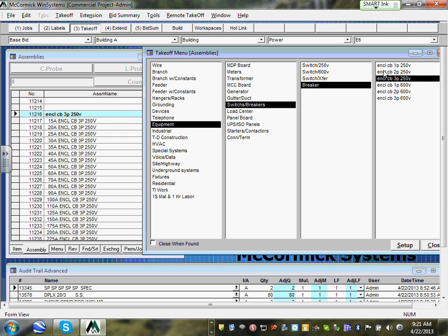Reminder, my friend, this project is 208. If it's a 208 system, we take it as 250 maximum voltage. You don't go to 600. It's kind of overkill a little bit. Oh, the breakers in the panels, yeah.